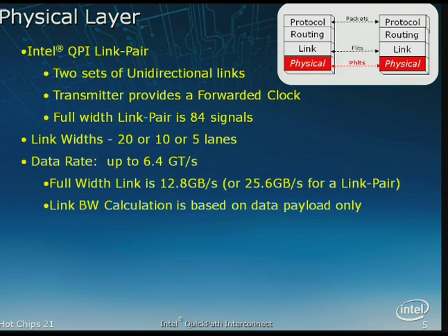And being the chairperson, this was not my decision, but this adds a certain level of confusion. We calculate bandwidth differently. The bandwidth calculation is on a by 16. When you look at this number, it's on a by 16 number, not a by 20. Notice our width is by 20 wide, but our bandwidth is basically only calculated on a by 16. Because ultimately, when you see some of the formats, we have set CRC off to the side, and therefore we don't count that as part of the overall system bandwidth.